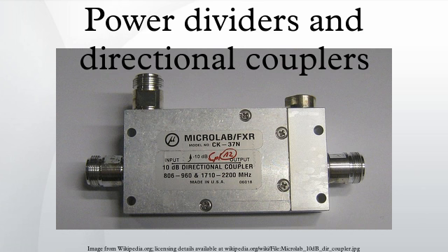The branch line coupler consists of two parallel transmission lines physically coupled together with two or more branch lines between them. The branch lines are spaced λ/4 apart and represent sections of a multi-section filter design in the same way as the multiple sections of a coupled line coupler, except that here the coupling of each section is controlled with the impedance of the branch lines. The main and coupled line are of the system impedance. The more sections there are in the coupler, the higher is the ratio of impedances of the branch lines.